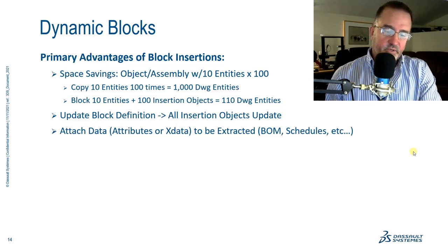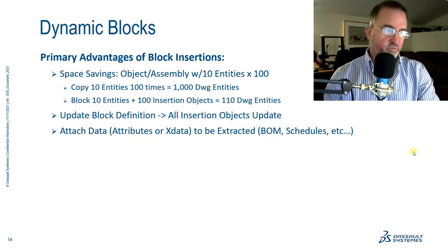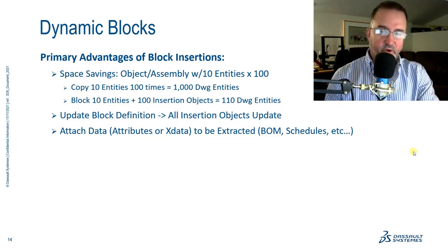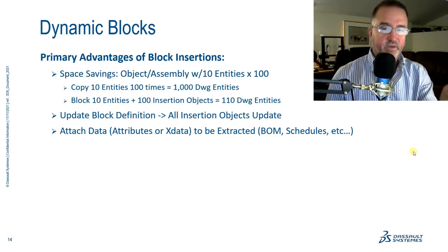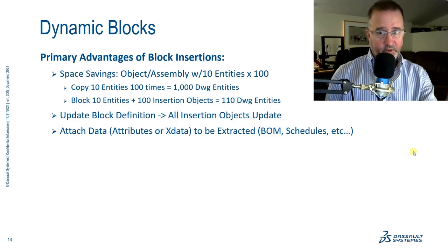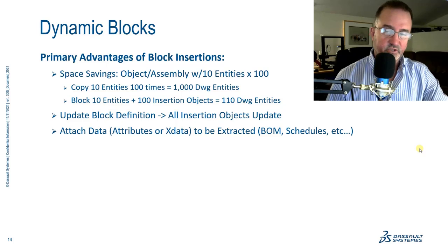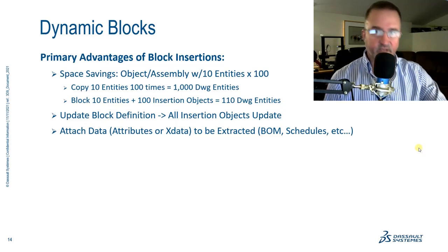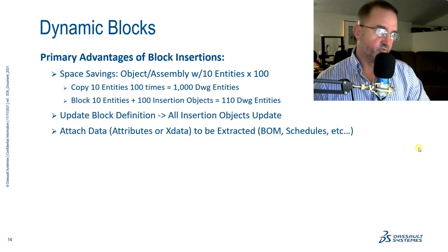Now, I can also attach attribute data to a block, or as you will see later in some of the other examples, I do teach you how to use Xdata as well. But let's say we want to attach some information to that block. Well, if I do it in the correct manner, I can automate either bill of materials, schedules, different data extractions. I can take all that information from those blocks that have been scattered around my drawing and extract that out and automatically put it into a bill of materials or a schedule and so on. So very powerful when it comes to data analysis, collecting data, collecting information about those blocks. Very, very powerful.